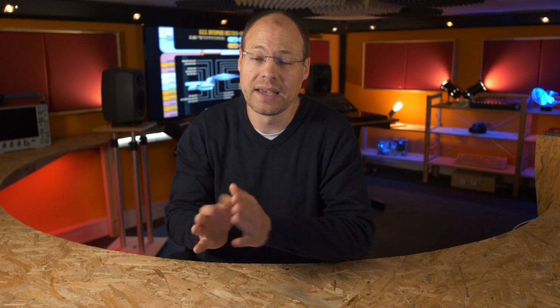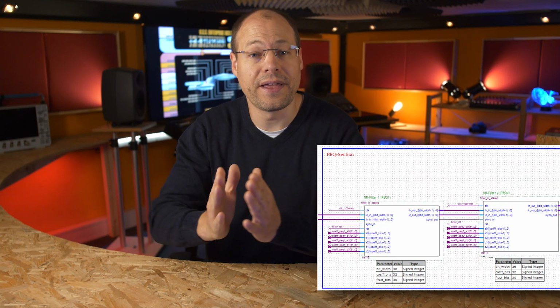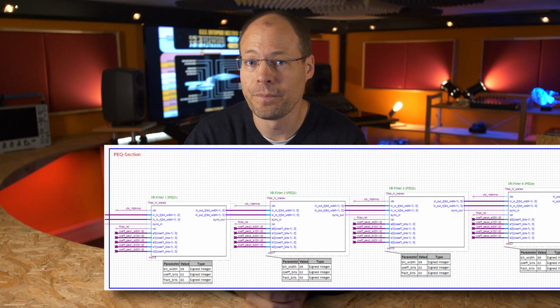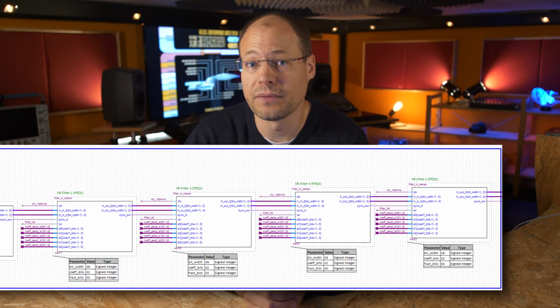That means we can work in real time with only one sample latency, as 20.8 microseconds between the individual samples are way longer than our process time. For a stereo EQ, these calculations have to be calculated twice, but can be carried out in parallel, one of the biggest advantages of an FPGA. For several EQs, the output of one EQ block is then connected to the input of the next EQ. For 5 equalizers, we then need around 300 nanoseconds, but this is still way below the 20.8 microseconds.